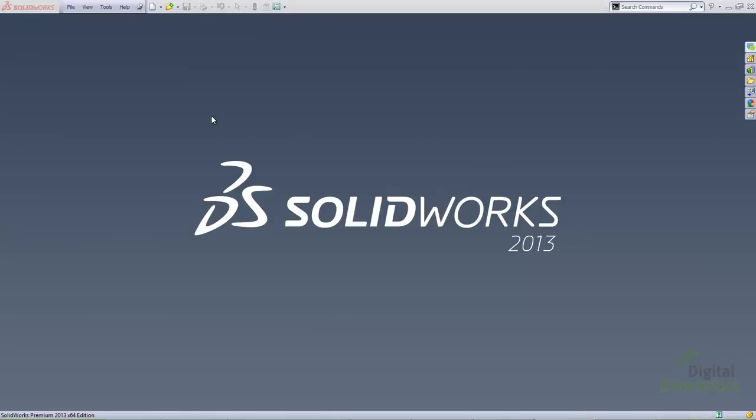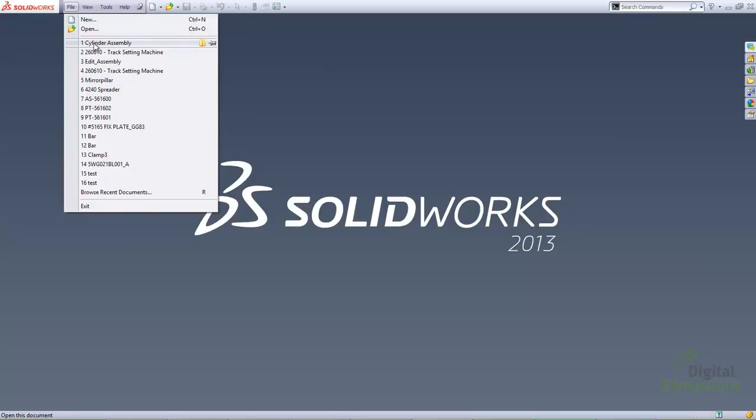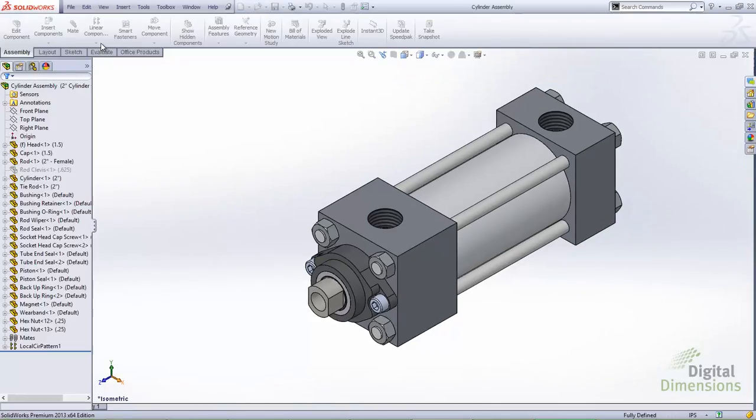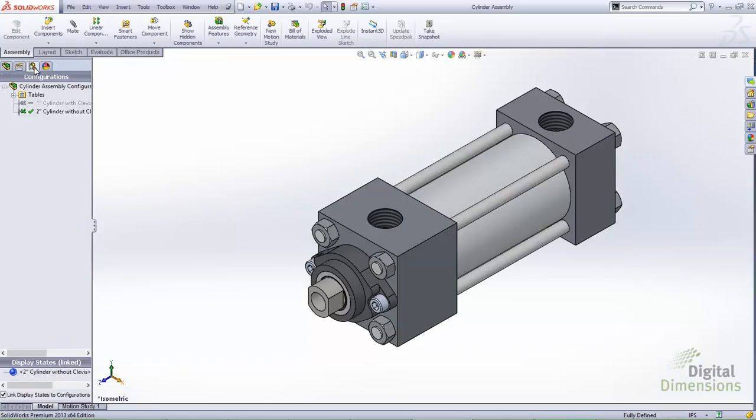So the next enhancement to large assemblies that I think is worth pointing out is an enhancement to multiple configurations. When you have an assembly with many different configurations, performance becomes an issue. One thing that we've done about this in the latest release of the software is support purging configuration data from a model. Maurice went over this in great detail in his configurations CADcast, but I want to go over it again here as well, maybe just a shortened version of that.